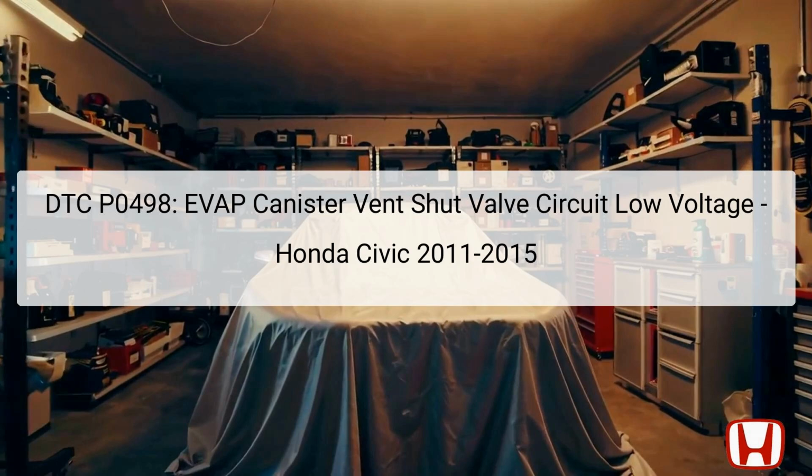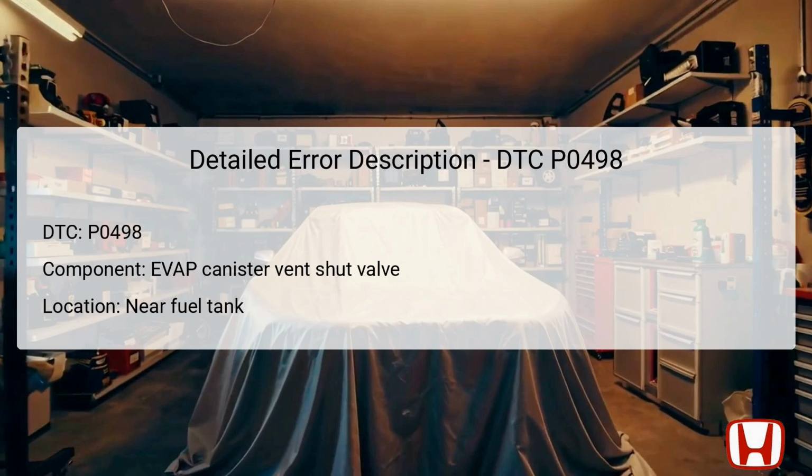DTC P0498 indicates an issue specifically with the EVAP canister vent shut valve circuit. This component is responsible for managing fuel vapor emissions from the EVAP canister located near the fuel tank. It operates by opening and closing in response to specific engine conditions, ensuring that fuel vapors are directed correctly into the engine during combustion. The location of this valve is critical, as it must effectively interact with both the canister and the engine control module, ECM, to monitor and minimize emissions.